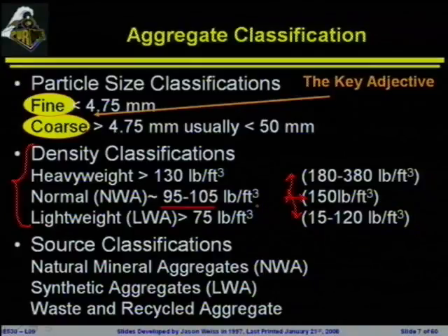All right, we will find out that there are concrete canoes, concrete battleships that use lightweight aggregates, but the big thing that drives lightweight aggregate, at least historically, has been reducing the self-weight of the concrete. If you're designing a bridge and the majority of the structure is to hold the structure itself up, that's not a very efficient design. So they switched to lightweight aggregates to make the girders lighter, make the bridge deck lighter, so that you can make the bridge design much more elegant.